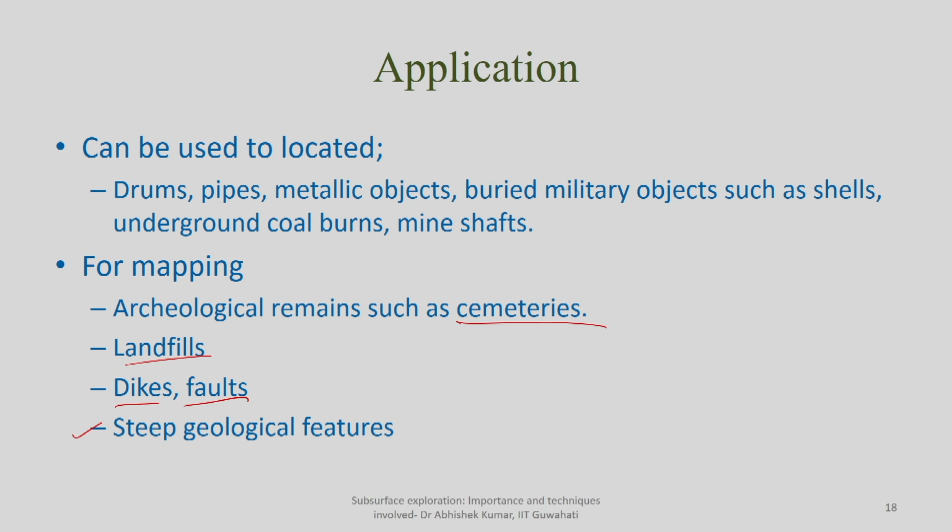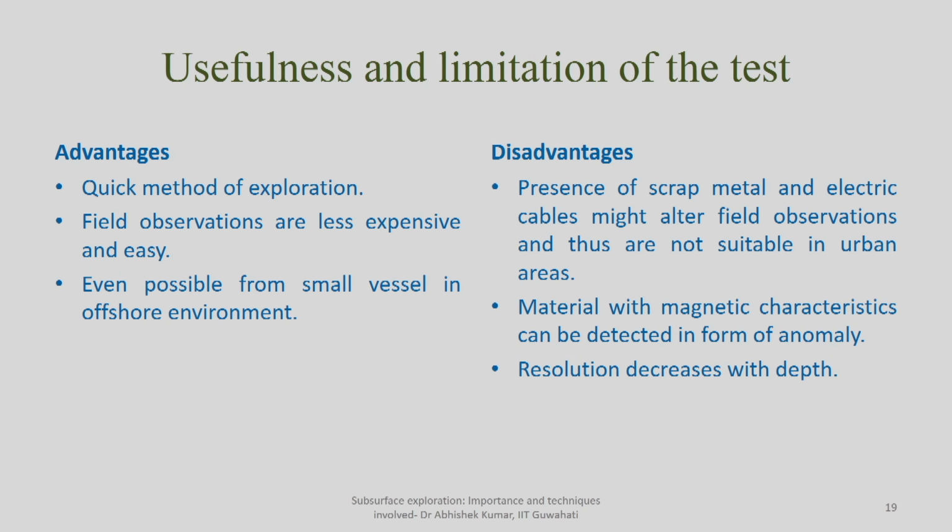Steep geological features also contribute to significant change in your magnetic properties. So, usefulness and limitation: the test is a very quick method of exploration, and field observations are very easy and less expensive. You can do the test even from a small vessel to a large vessel, particularly if you are doing it for an offshore environment. Even nowadays, when people try to understand the seismic characteristics of a region, such tests are very well used to understand the ongoing seismicity or identification of new faults. So, the magnetic method also can be used.